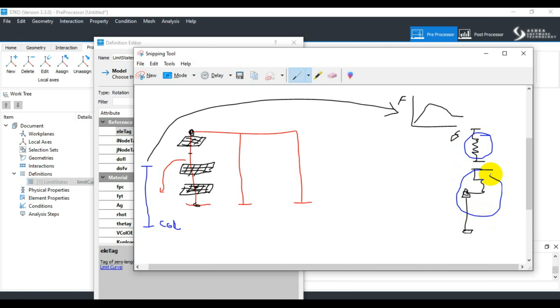When used in series with the beam column elements, the uniaxial material adequately captures the response of the reinforced concrete column during shear and axial load failure, and you can then use this approach with your experimental studies to validate your models. You can also develop your own material based on a multilinear approach in your analysis models and explore the various capabilities of OpenSees in your analysis.